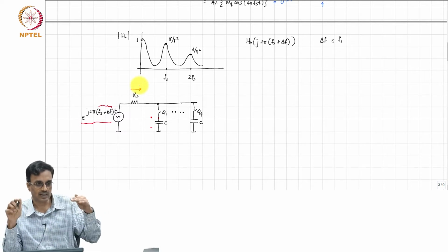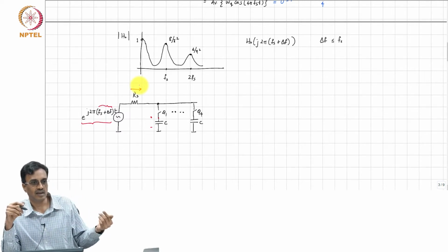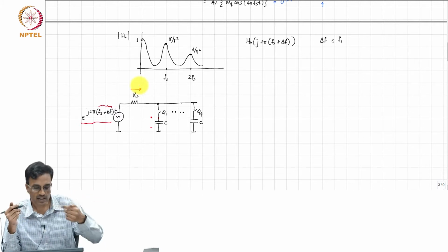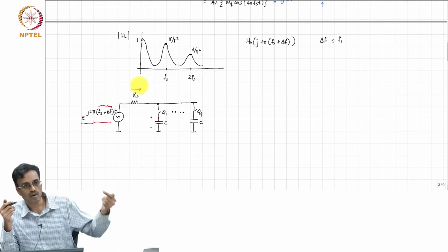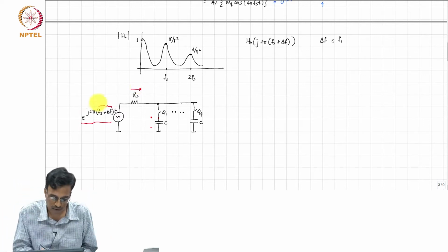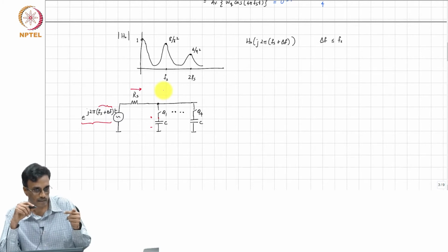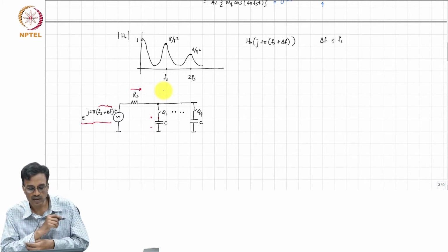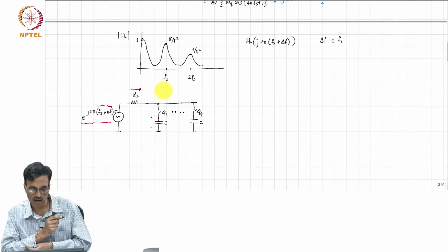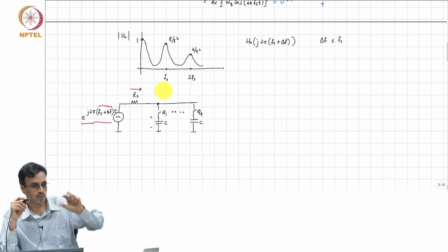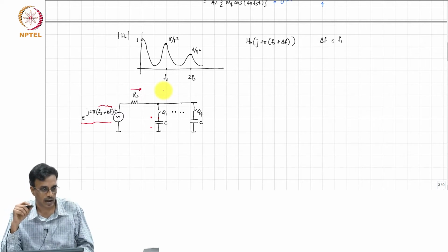Whatever voltage results is a result of the equilibrium between two opposing effects. One is the mixed down version of the high frequency current flowing through RS, right, and the other one is the loss of charge from the capacitor due to this periodic connection with RS.